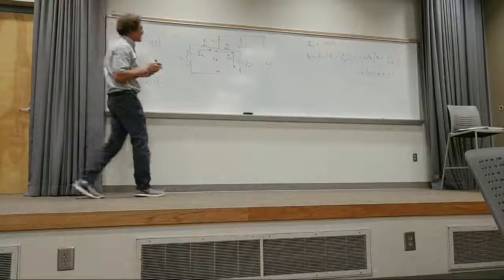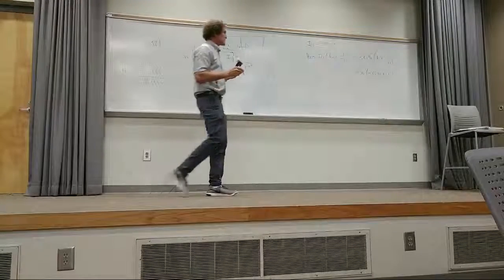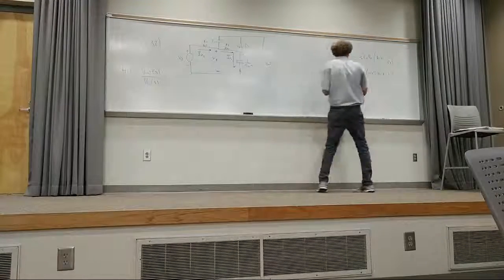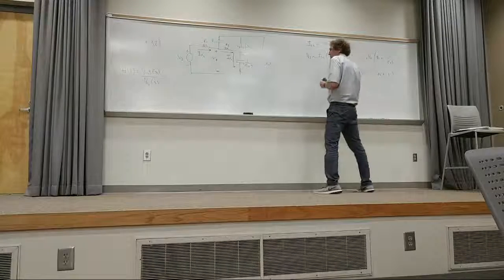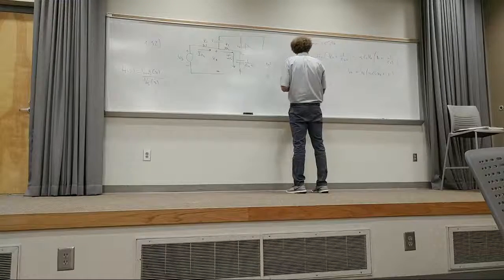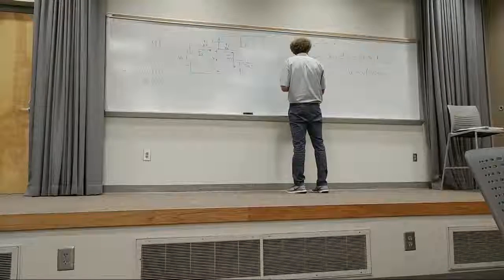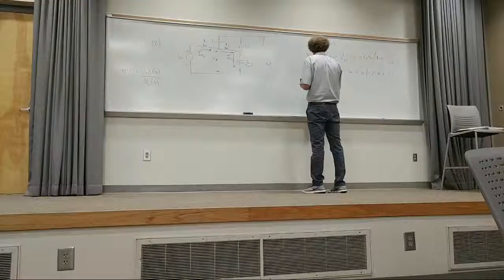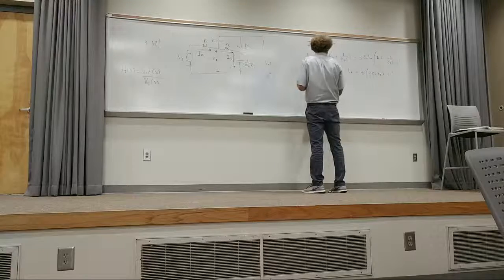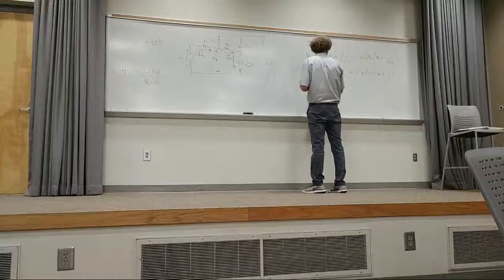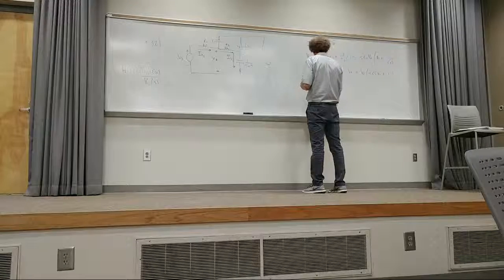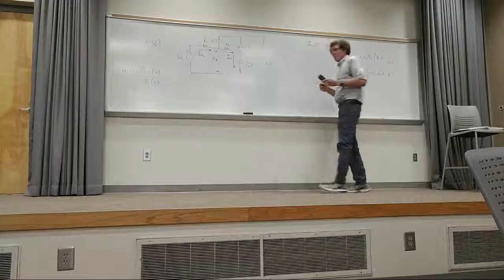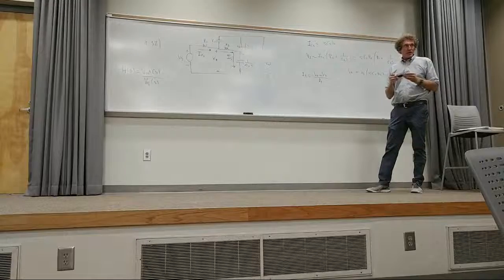All right, now when I look at that, I can put this down. This is going to be V2. And when I put down IR1, I see that's equal to what? Vs minus V2, over R1. Do you agree with me? Agreed?